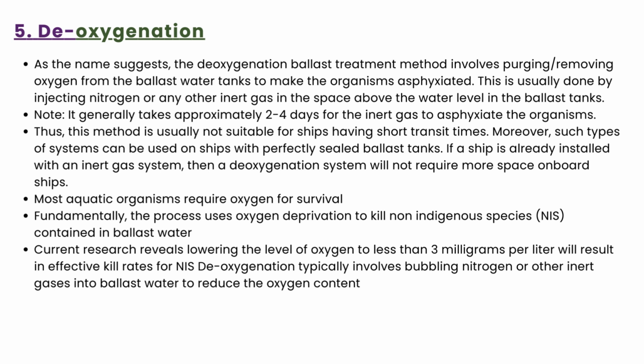Okay, it normally takes about 2 to 4 days for inert gas to asphyxiate the organisms. Now remember something, in other technologies the time period is not that long. Here in de-oxygenation the period is a little longer. This method is usually not suitable for ships having short transit time. Moreover, such a system can be used on ships with perfectly sealed ballast tanks. If a ship is already installed with an inert gas system, then a de-oxygenation system will require more space on board ships.